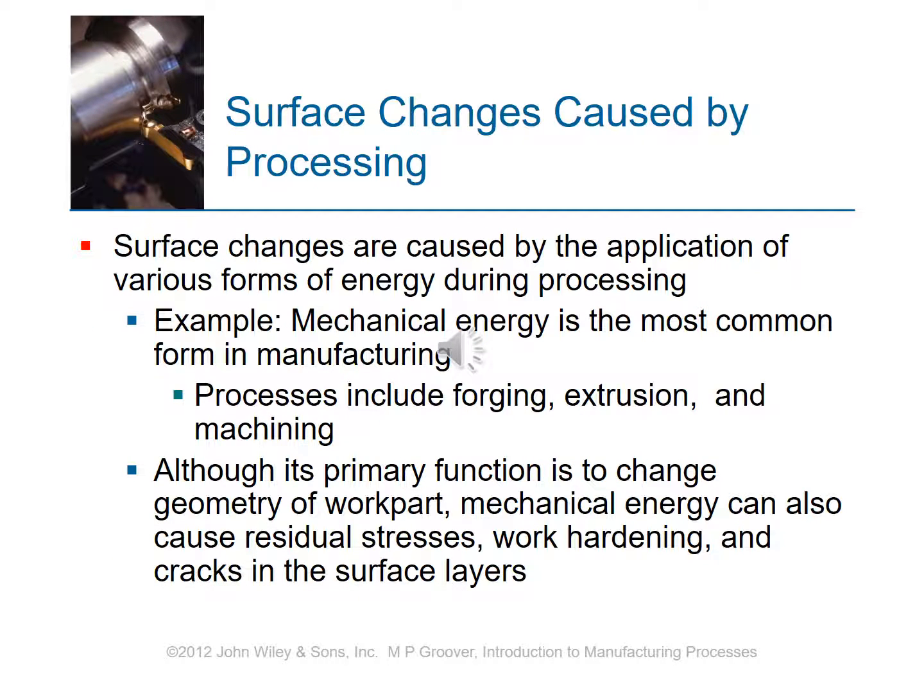As you work a piece of material, you're putting energy into it, and that energy can be stored as residual stresses. You can do some work hardening. You can cause cracks. You can knock out inclusions. There are all kinds of things you can do while you're processing it: forging, extrusion, and machining. Be careful with this. It's important that you're aware of it.